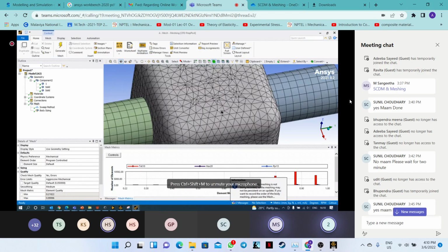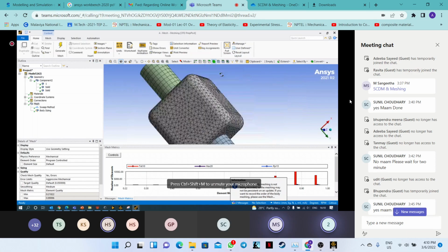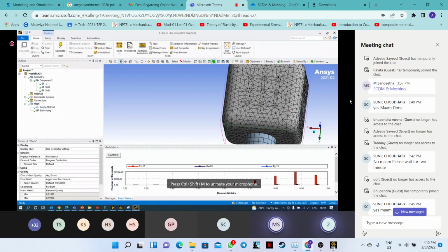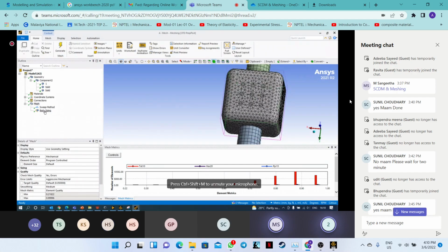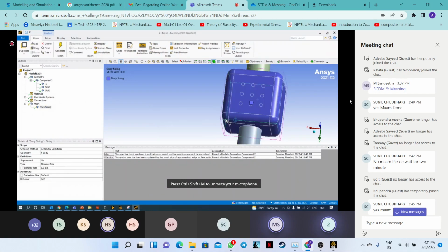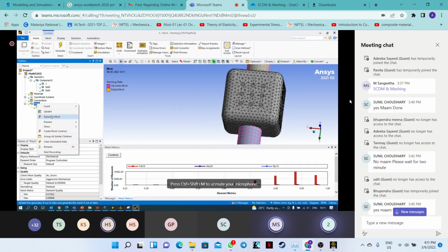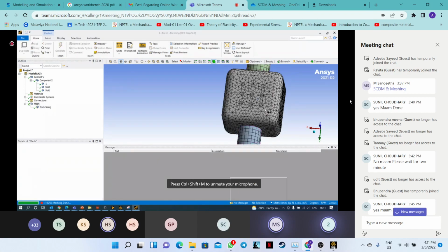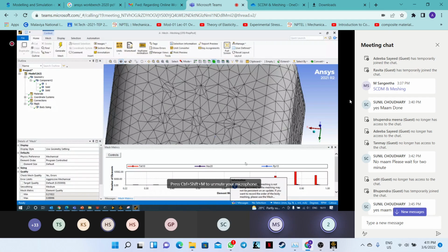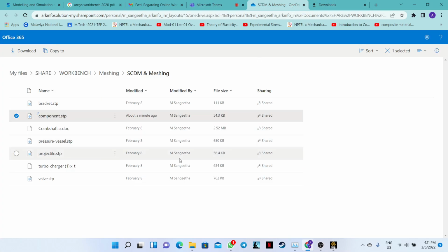Okay, so when I say generate mesh, I think capturing is quite okay here. I'm able to get good quality of element, right? So this would be my approach. And even as I said, this sweep method generation is not required. When you look at your simple geometries, if by default you are able to get good quality of elements, then why do you have to struggle in generating mesh? See, just giving a body sizing to this component was sufficient for me to work on this mesh, right?